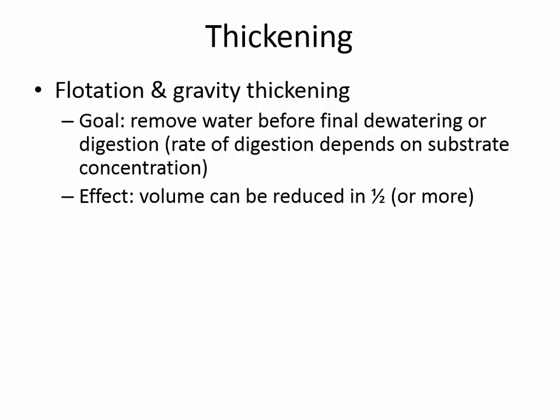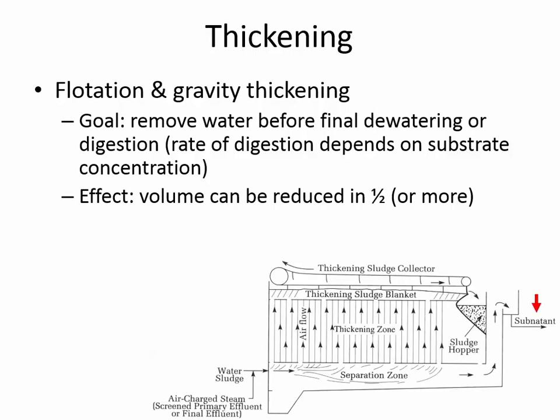All right. We want to make the sludge have less water, more compressing the solids altogether. And there's an interesting technical way to do that. It's called thickening. What you do is you have a tank that's pressurized. You're pumping the sludge into a pressurized tank. When you have a pressurized liquid, you can dissolve more gases in it than normal. Like if you have a can of Pepsi, you know that it's pressurized before you open it. But what happens when you open that can of Pepsi? The bubbles are starting to float up, right? That's what they do with the sludge.